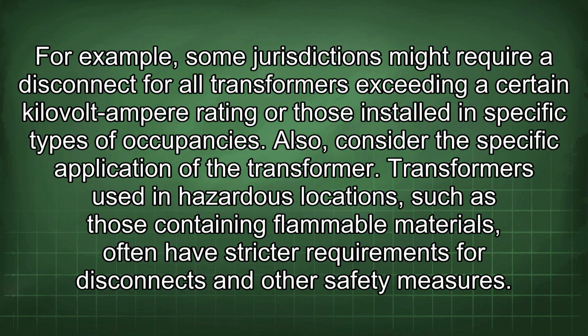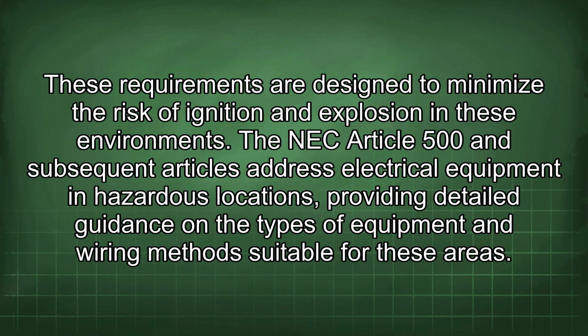Also, consider the specific application of the transformer. Transformers used in hazardous locations, such as those containing flammable materials, often have stricter requirements for disconnects and other safety measures. These requirements are designed to minimize the risk of ignition and explosion in these environments. NEC Article 500 and subsequent articles address electrical equipment in hazardous locations, providing detailed guidance on the types of equipment and wiring methods suitable for these areas.